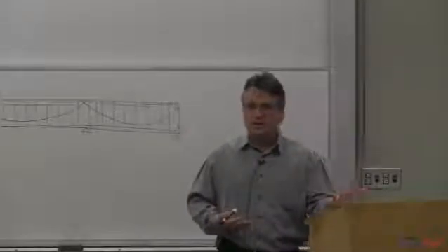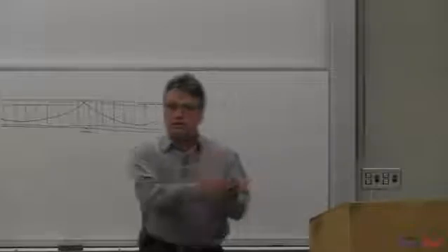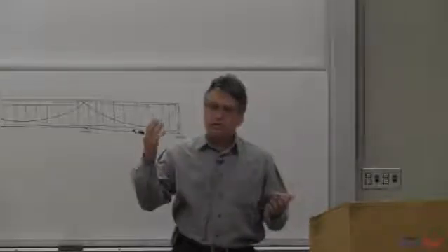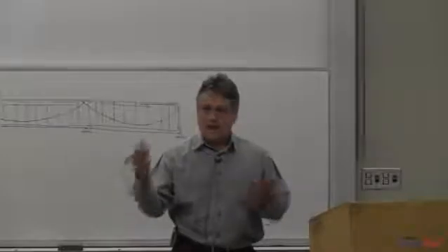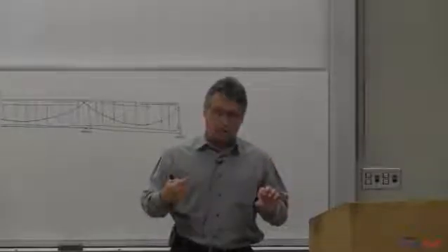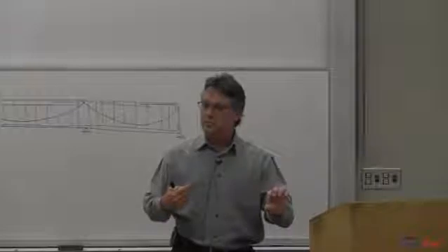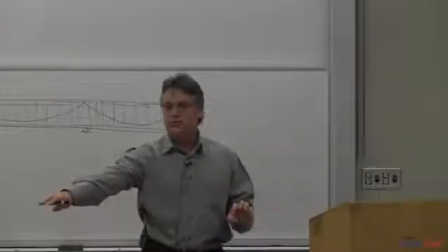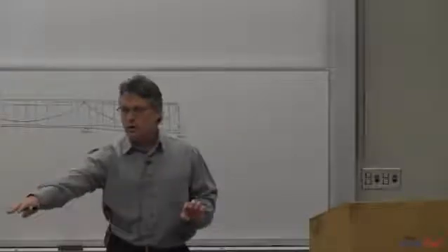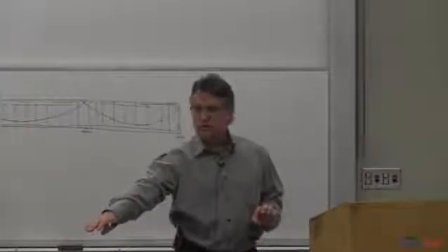You've got a design development set coming on a certain date on one project, and you've got a 75% construction document submittal coming on another date, and it's up to you to prepare enough calculations for the design development set, get enough information to the draftsman, at the same time getting enough information for either the building department submittal or the 95% submittal.